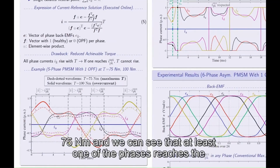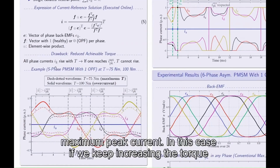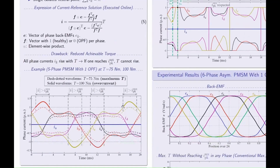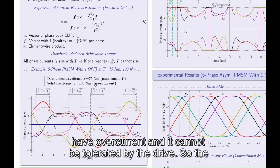And we can see that at least one of the phases reaches the maximum that is indicated as 1 per unit because it's normalized by the maximum peak current. And if we keep increasing the torque reference up to 100 Newton meters, as represented by the solid waveforms, we can see that since all the phase currents increase linearly, there are some parts where the phase currents are greater than the maximum limit. So we have overcurrent, and it cannot be tolerated by the drive.